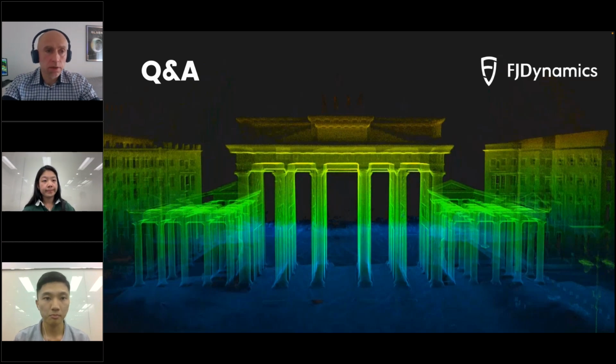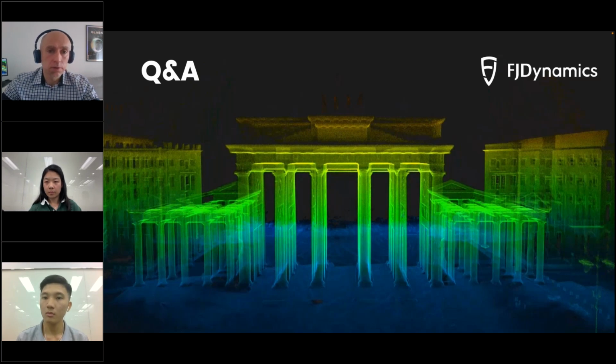Split your object into smaller scans, and try to scan the most difficult parts at the end. Cut out the most difficult rooms, maybe the smaller ones, and scan them separately, and if needed, use the real-time point cloud, as I said in the first tip. For small rooms like toilets, I usually use the real-time point cloud.